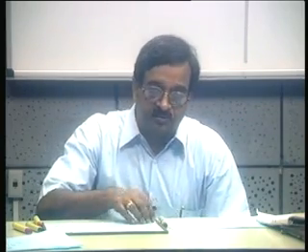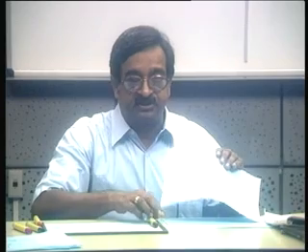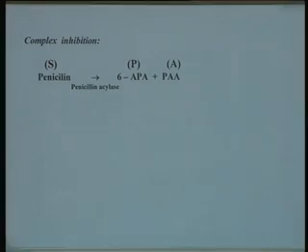Now, these are the standard kind of inhibition patterns which we are familiar with, substrate inhibition or product inhibition, which is non-competitive or competitive. I do not consider it necessary that a third inhibitor be added. It can be either substrate or product which can cause inhibition and which has to be taken into account while making a reactor design or while analyzing the reactor performance. Now, another situation arises which is much more complex. Of course these are theoretical situations which are comparatively simpler. In many practical situations the inhibition patterns are usually complex, they are not as simple.